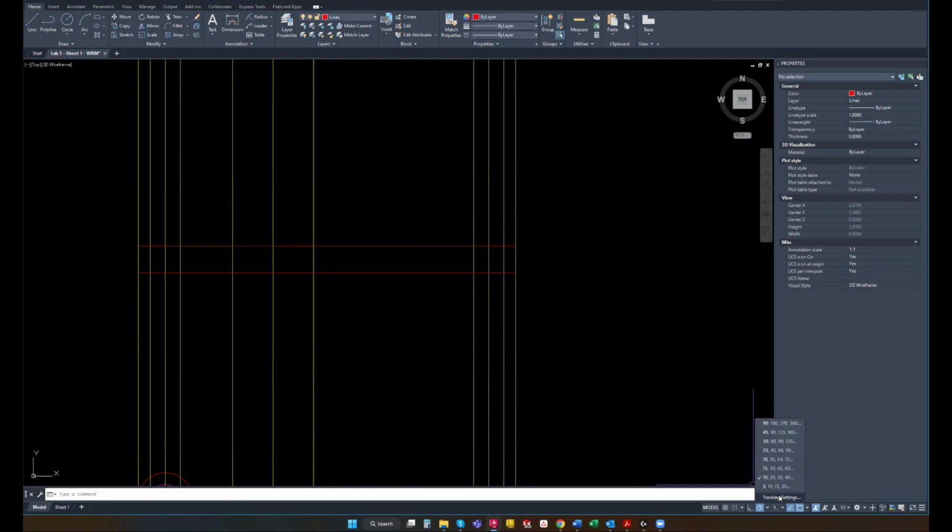Alternatively, and I'm going to set mine. Oh, there we go, right there. Alternatively, you can grab your line tool, start here at the bottom, and then just stay within this 90-degree quadrant here. Just kind of hover in this area. And I'm going to say just an arbitrary number. So 1 inch, tab, 80 degrees. And that will give us a 1 inch line at 80 degrees from this point. So this point, drag out this direction is 0 degrees. This is 90 degrees. So that's what we did there.